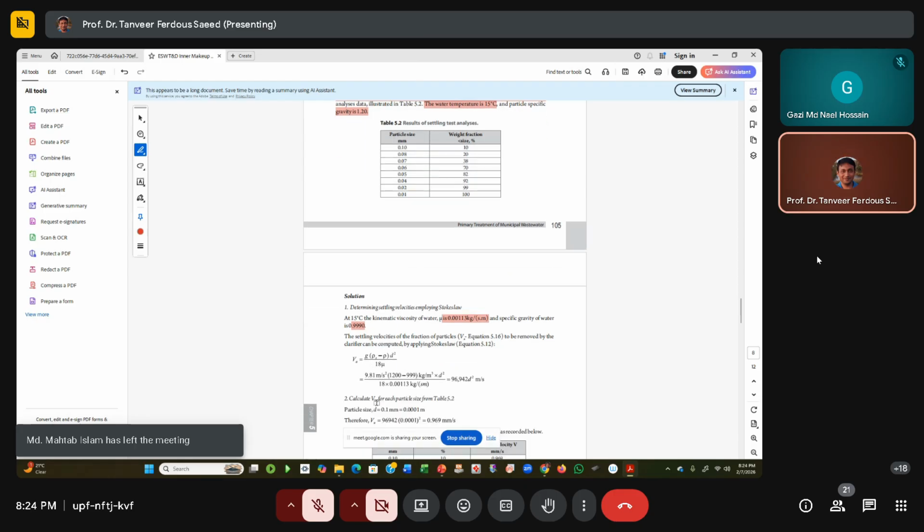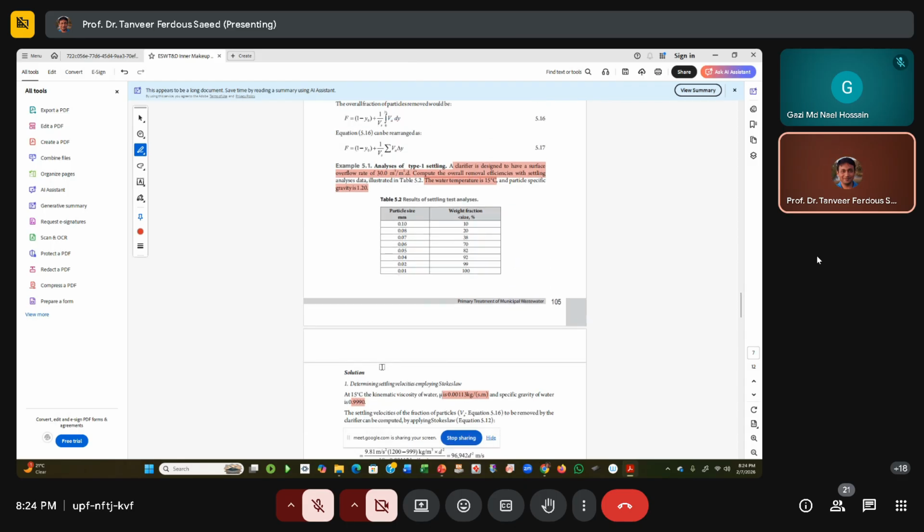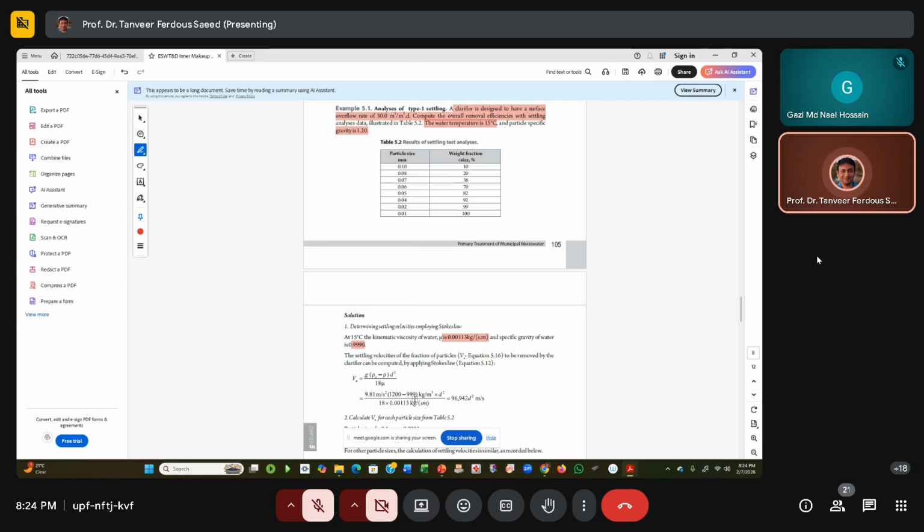We already went through it. So we know this value, the density of the particle, which should be given here. It must be given in the problem. So we write it in kg per meter cube, to be converted, and then the density of water, this is 0.990, specific gravity, and we converted it. The kinematic viscosity is directly given. So we get this equation, but the variable here is diameter. We do not know it, but again, the diameter is given here, the particle size.